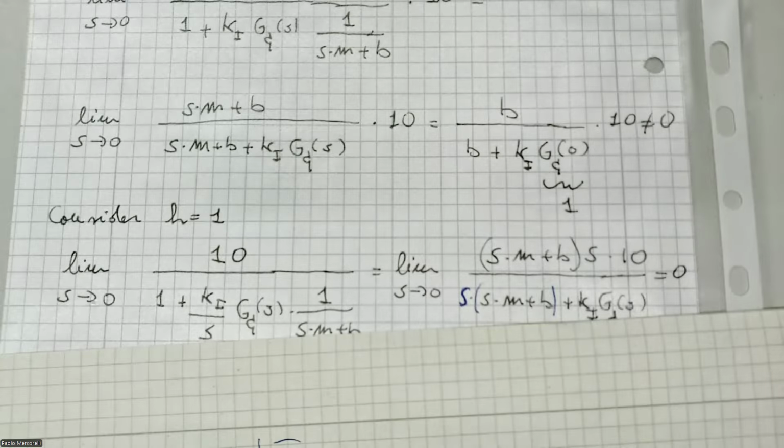If I want to park, do you remember at the beginning I told you we can switch from ramp and then constant? If I want to park, I want to follow at the beginning the ramp, I need an integral in the displacement control, in the first part of the displacement control. Because the principle of the internal model says I have to replicate in the open loop GOL exactly the Laplace transform of the reference.